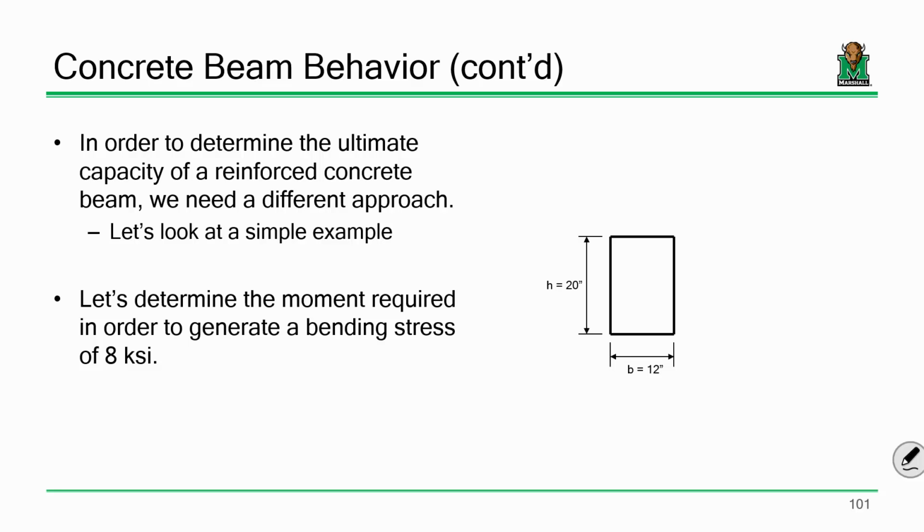I want to frame it around this. I've got a beam. The dimensions really don't matter, but I've got a beam that's 12 inches wide. It's 20 inches tall. And I want to ask you what moment is required to generate some stress. We'll say 8 KSI. Okay. There's 2 ways of doing this problem.